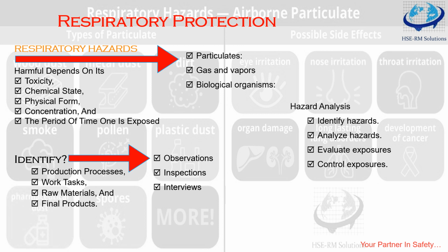Examples of engineering control include isolating the production process so that employees are not exposed, installing an exhaust hood to remove air contaminants, using wet methods to reduce the exposure to airborne dust, and integrating dust collection systems into cutting and grinding equipment. So these are all engineering controls.